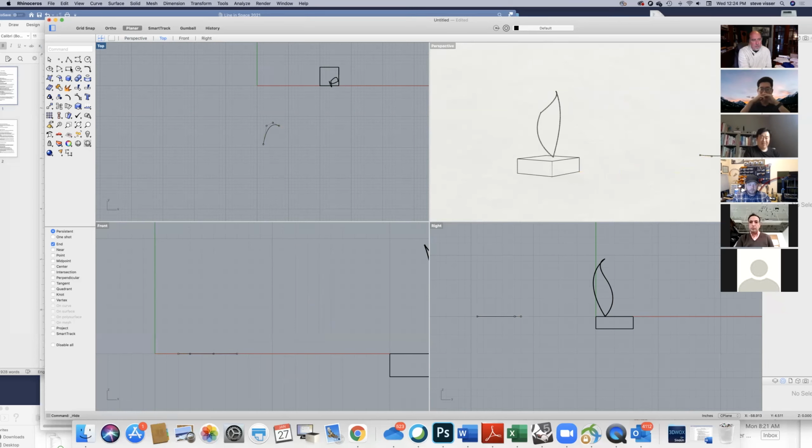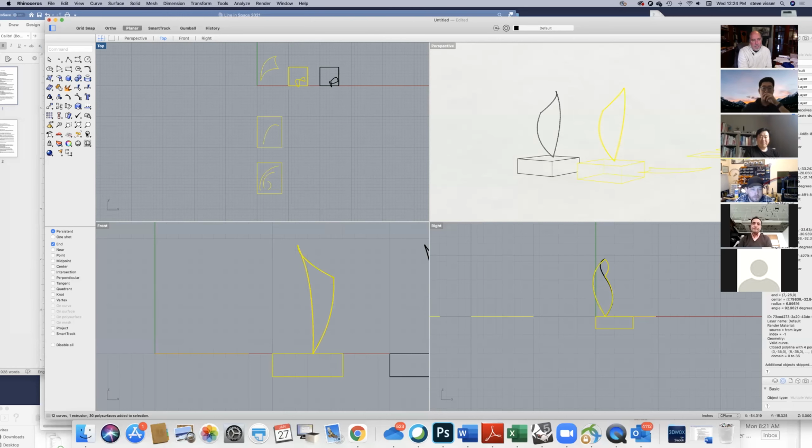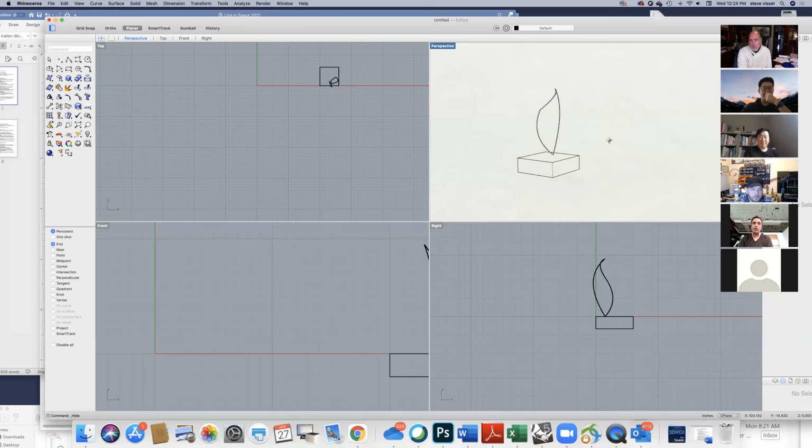I've got to turn my edit points off. Let's hide that one as well. And then to bring them back, it's just right click on the light bulb and they all come back. So they can hide all of those, and then they can easily create their surface here without accidentally moving other pieces around by clicking on them when they didn't intend to.